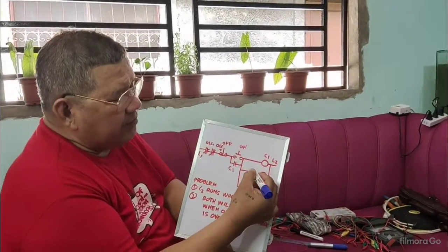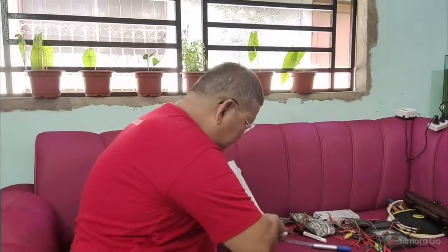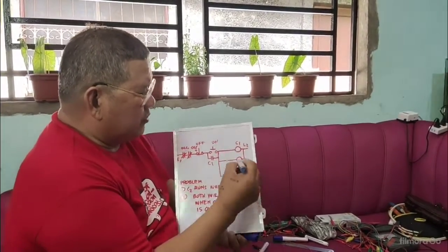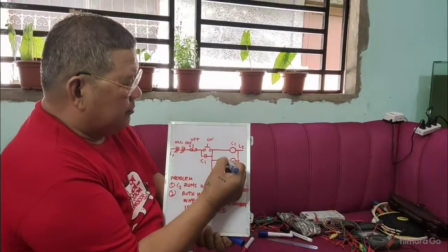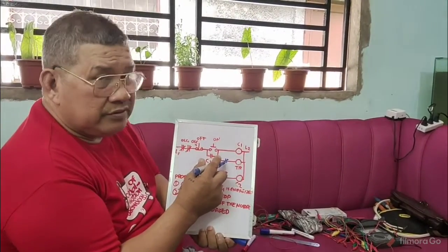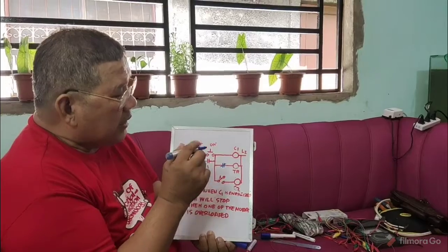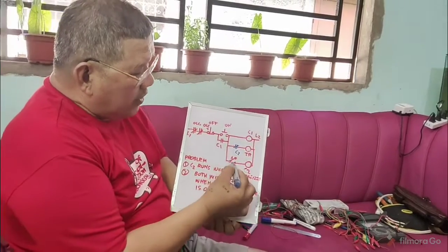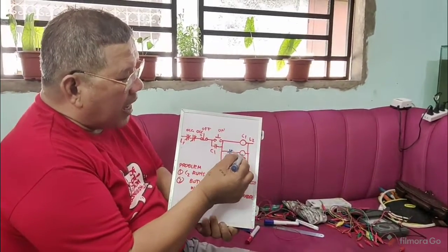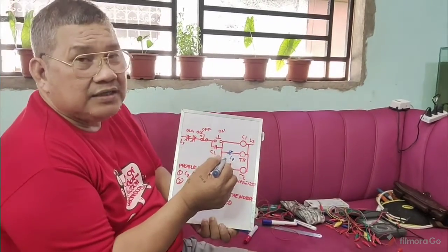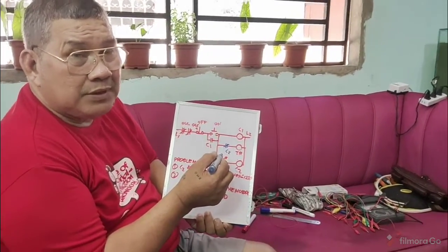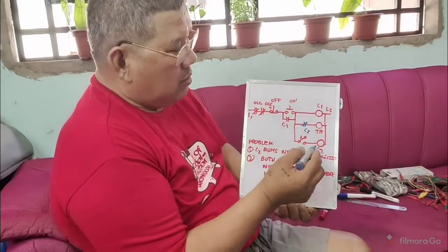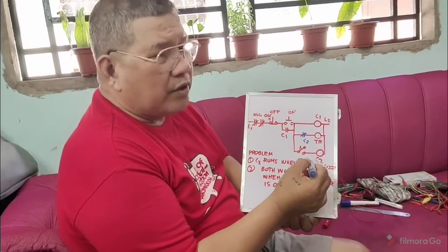Okay? So this time, you will place here a normally close auxiliary contact. Coming from where? Conveyor 2. So when this is energized, of course this will open and this disconnects the time delay relay magnetic coil. So once this is disconnected, what will happen to the contact here? It will go back to normal position. Then what will happen to your conveyor number 2?